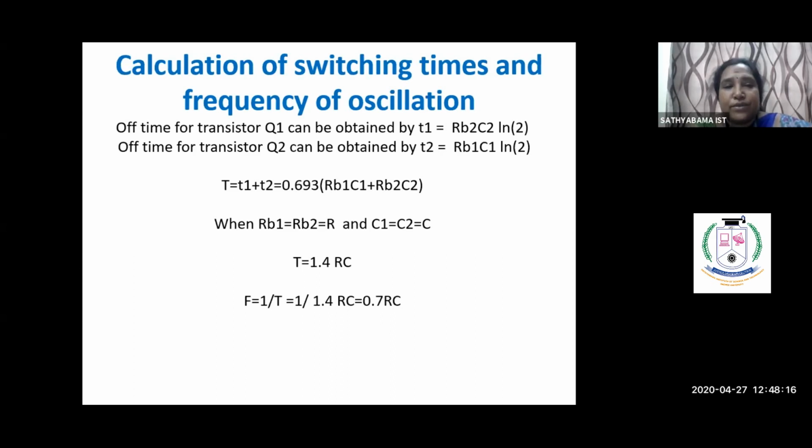Okay, so just to remember this switching calculation while we are doing the design. In the astable multivibrator, the first thing I have explained is the description. In the description, just remember only two points. When the circuit is powered, one transistor is on and the other transistor is off, and to change this state, we have to use the charging and discharging concept. Then we obtain the next state.